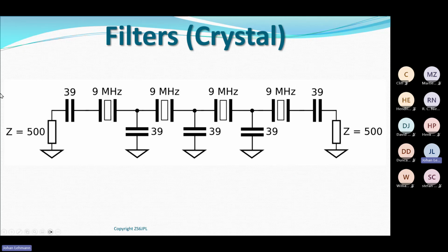So in any radio, you would find things which they call crystal filters. They are incredibly sharp band pass filters. It won't tolerate much below 9 megahertz, and it won't tolerate much over 9 megahertz either. And this one is a 4 pole crystal filter, which is really, really sharp like a knife's edge to pass 9 megahertz from this side of my circuit to that side of my circuit.